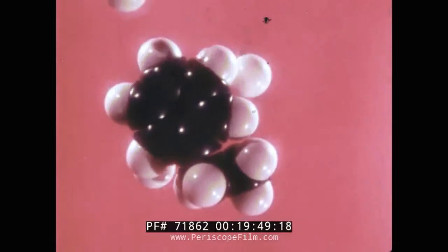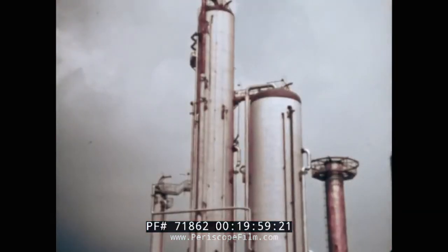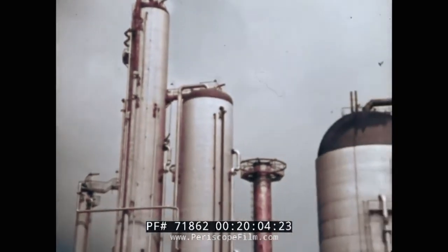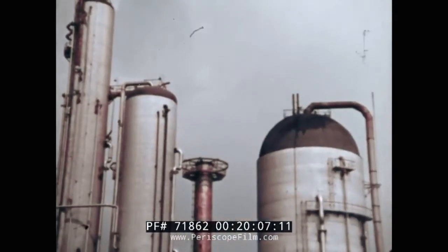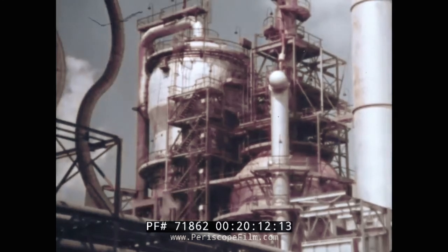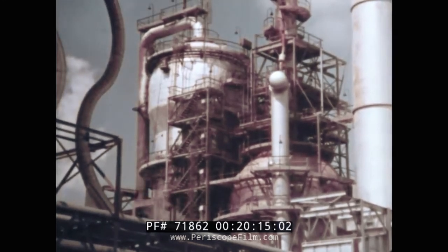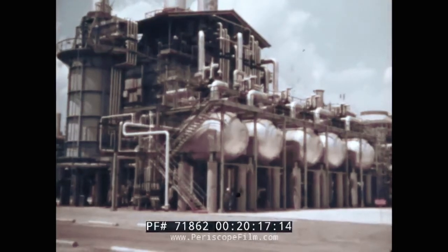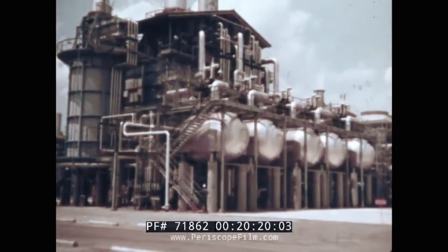During most of these reactions, a lot of hydrogen is released. Its presence not only inhibits the formation of carbon on the catalyst, it is also valuable for use elsewhere in the refinery. These, then, are the principal refining processes: crude distillation and vacuum distillation, which separate crude oil into various products; cracking, which converts heavy oil into high-octane gasoline, and reforming, which converts straight-run gasoline into high-octane gasoline.